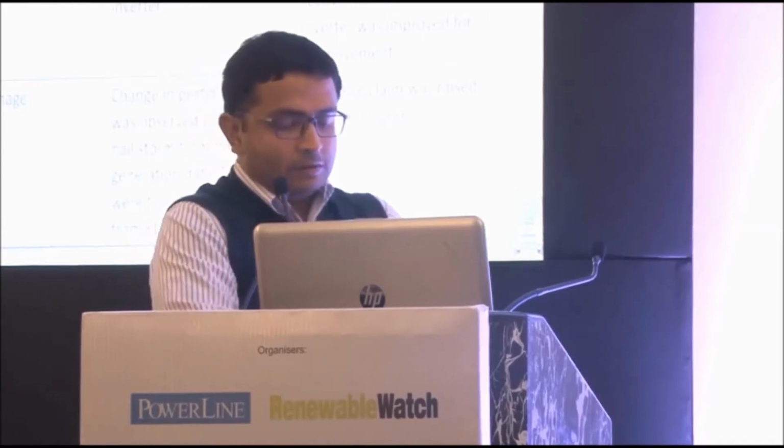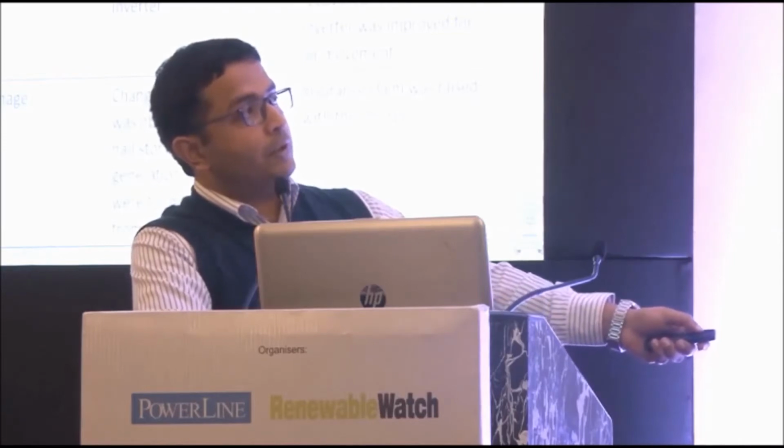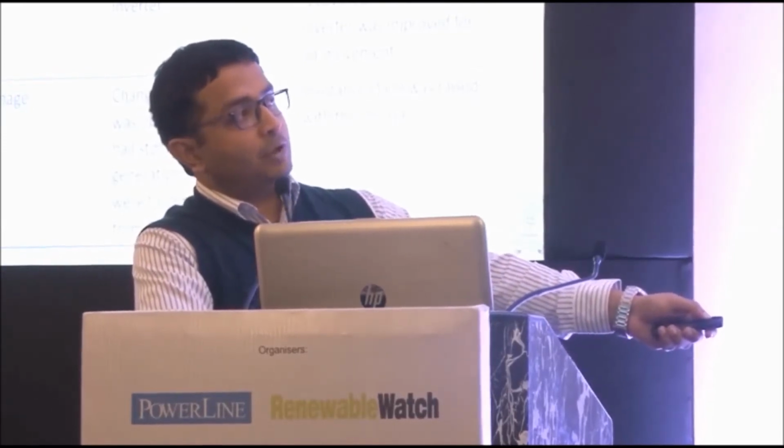I'll just quickly discuss some of the case studies for diagnostics. These are also again from PV Diagnostics, why their team was called and what was the issue. As you can see here, these were some of the issues why they were called, right? There was low PR, and then they found there was high PID, and then they implemented the potential induced degradation reversal solution there.